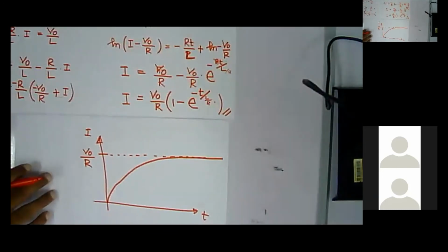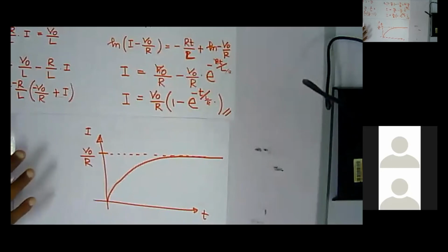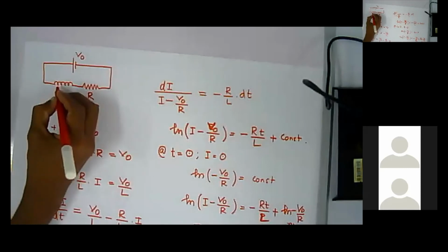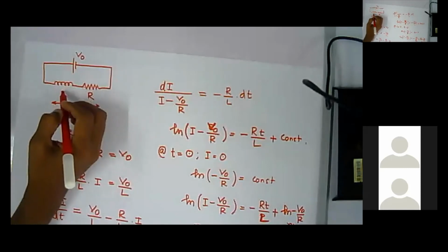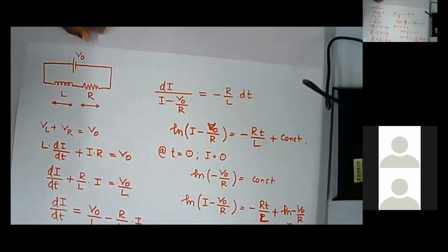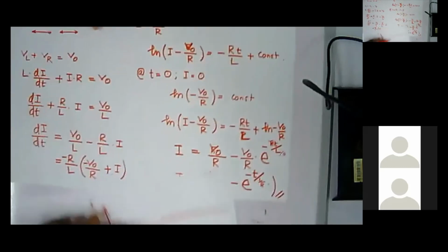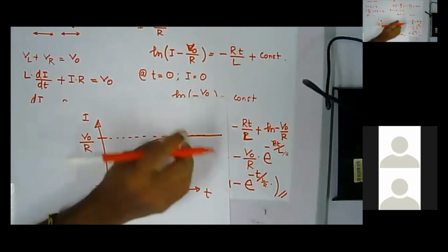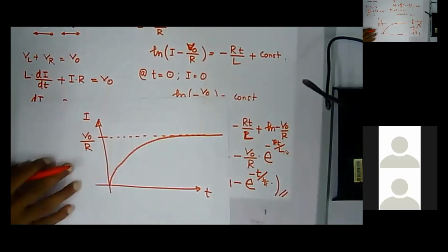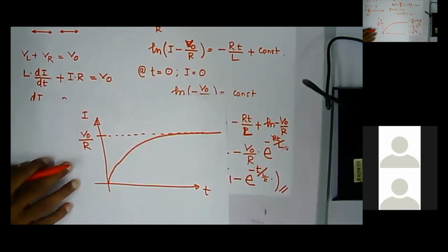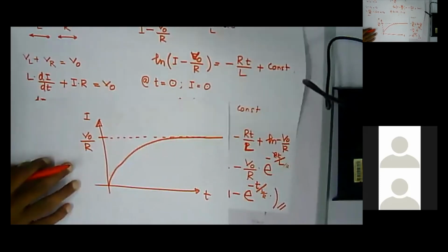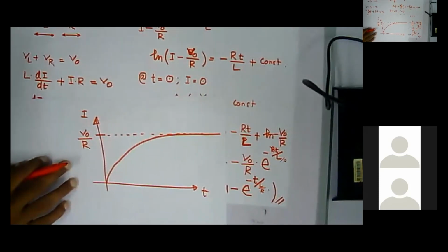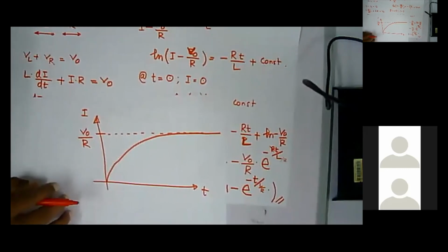So after the inductor is fully charged, right? So we can say that when you connect an inductor to a DC, until it's storing the magnetic field, there will be a change in current, right? Once it is fully stored, then there will not be any voltage across the inductor, or the inductor will act simply as a 0 ohm resistor, right?